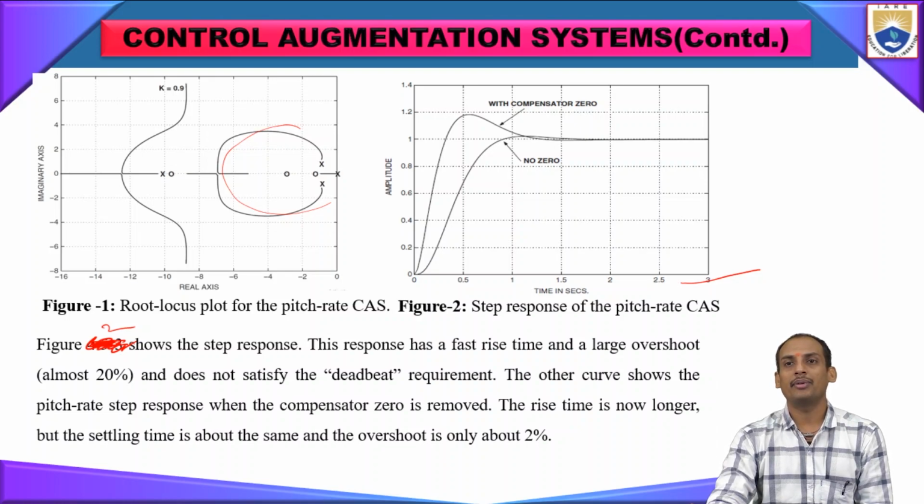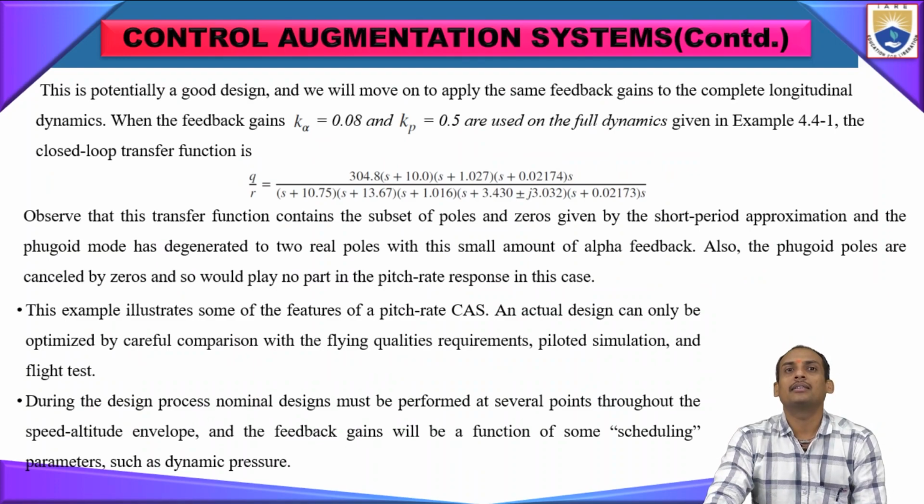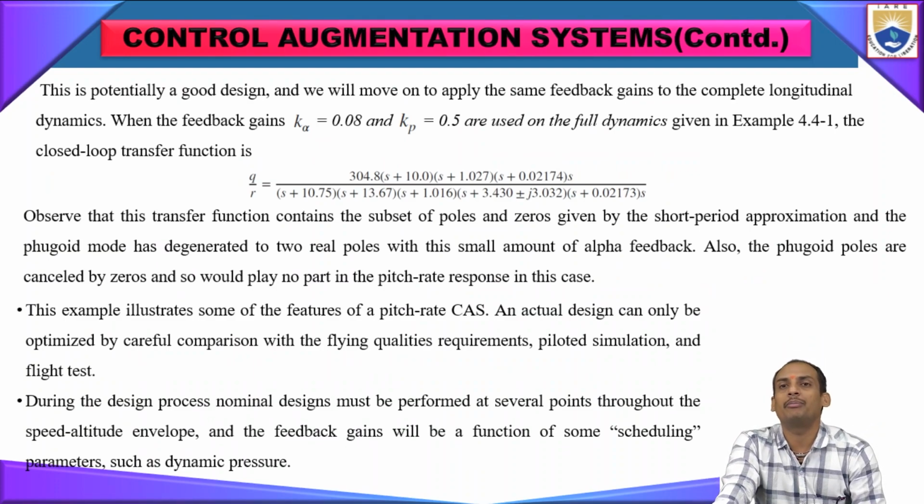So the rise time is now longer, but the settling time is about the same, and the overshoot is only around 2%. So this is potentially a good design.